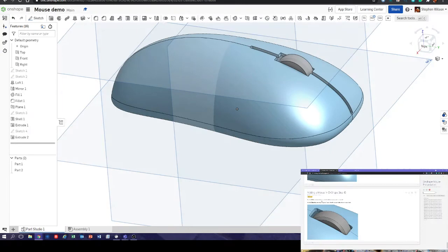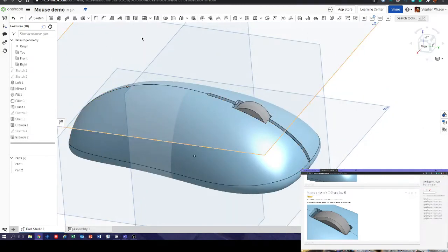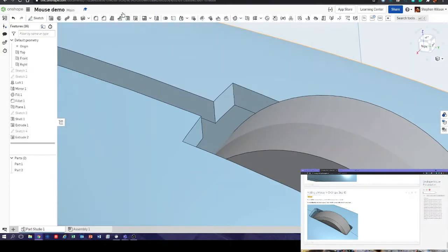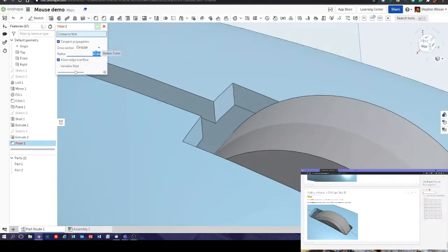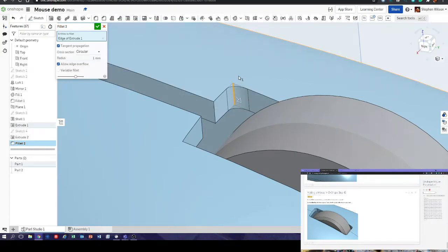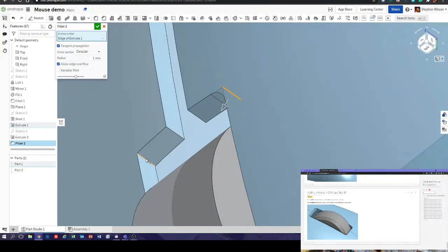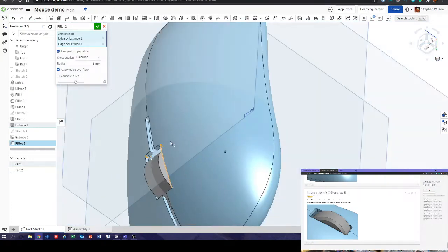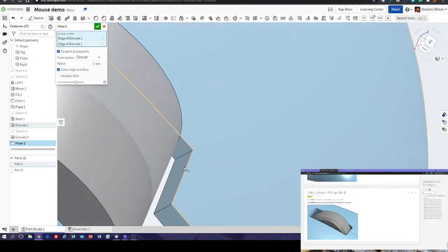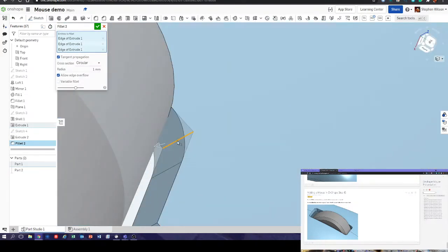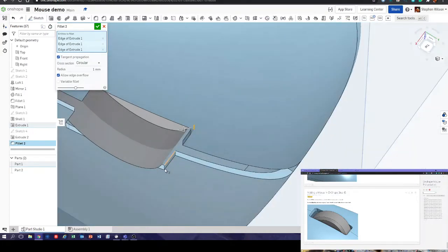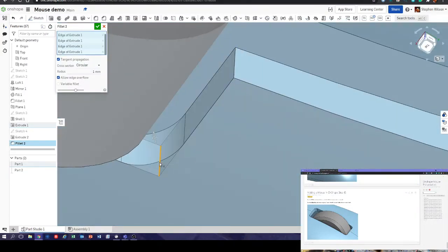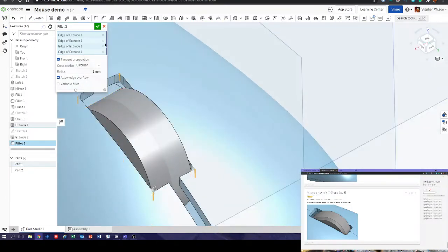Okay, use the fillet command to put a 1mm chamfer on the slot, so that's in the corners there, and the chamfer for the mouse wheel. Okay, so I'm going to have to zoom in a bit so we can see what we're doing. There's the fillet command. Let's set that to 1mm, not 5mm. 1, excellent, and 2, and 3, and 4. Okay, so that's that.